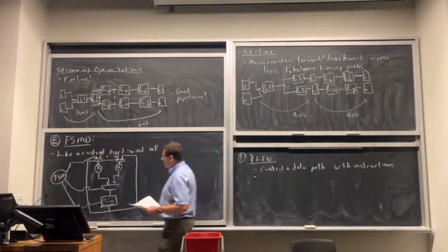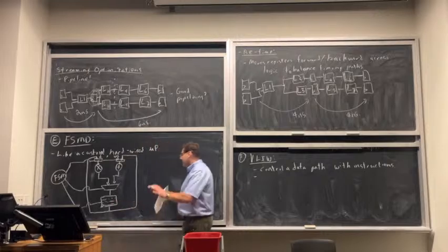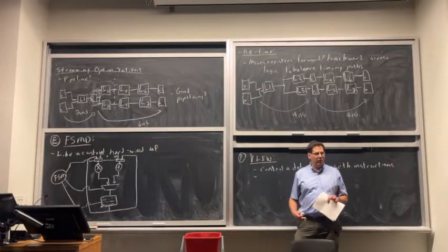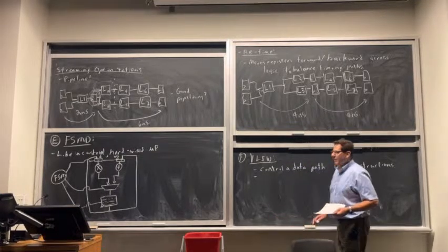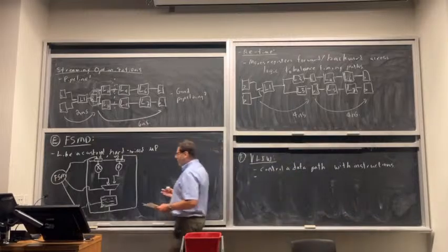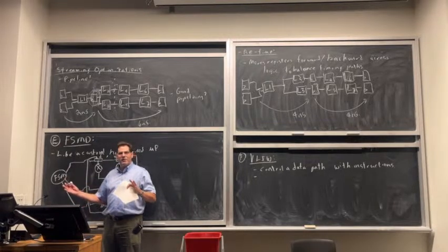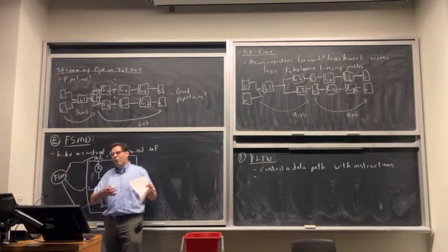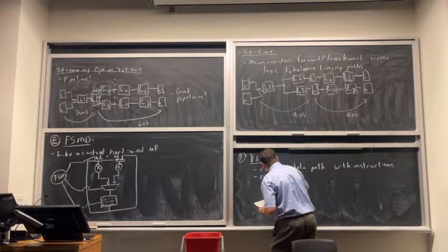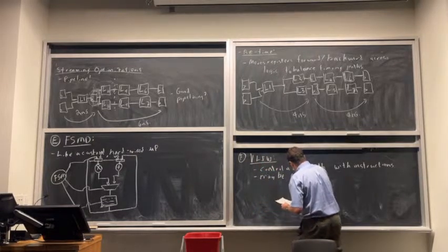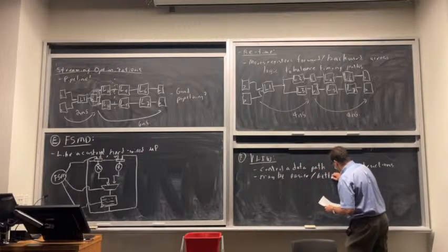If I'm doing just a few things, then a finite state machine is not too hard to code, and it's pretty efficient. If this data path gets big and my sequence of operations gets long, then the finite state machine might start getting hairy. And at that point, there's often a break point where it just gets not only easier to code, but even more efficient to, instead of building a huge finite state machine, think of it as instructions and store the instructions. It's not just easier, it can also be more efficient, so it can actually be better for wide and complex data paths.